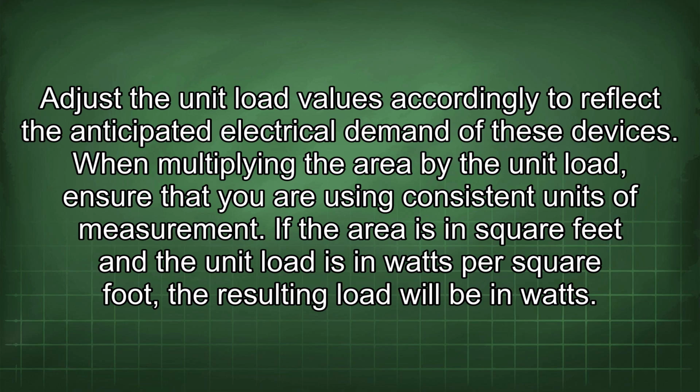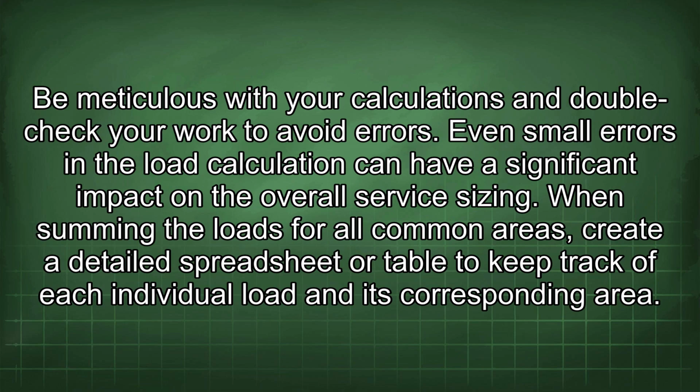When multiplying the area by the unit load, ensure that you are using consistent units of measurement. If the area is in square feet and the unit load is in watts per square foot, the resulting load will be in watts. Be meticulous with your calculations and double-check your work to avoid errors. Even small errors in the load calculation can have a significant impact on the overall service sizing.